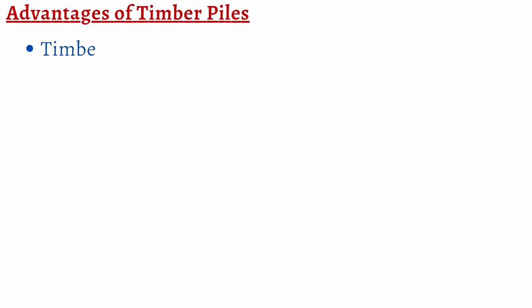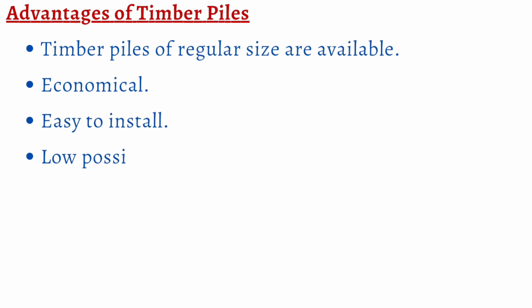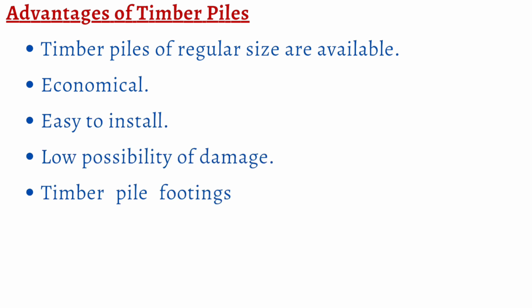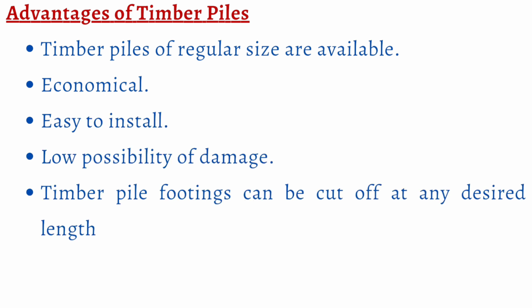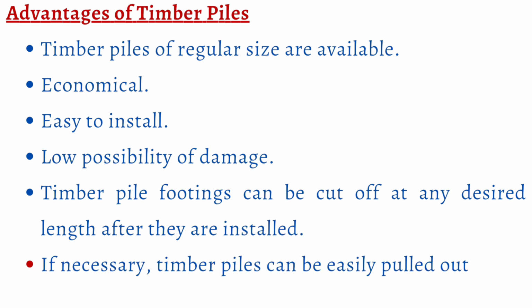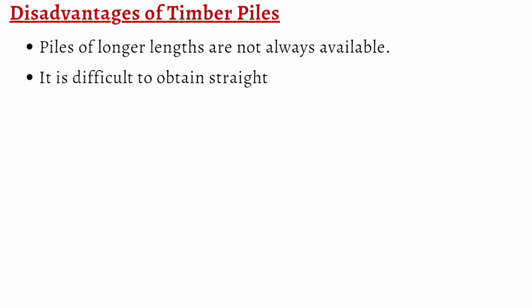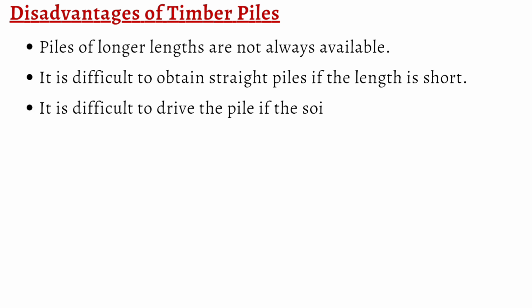Timber piles, untreated or treated with preservative; concrete piles, precast piles and cast-in-place piles; steel piles, I-section piles and hollow piles; then composite piles. Timber piles. Timber piles are the types of pile foundation that are placed under the water level. They last for approximately 30 years. They can be rectangular or circular in shape. Their diameter or size can vary from 12 to 16 inches.